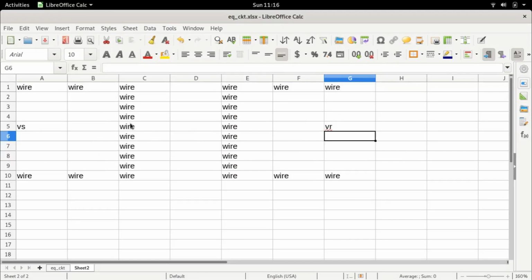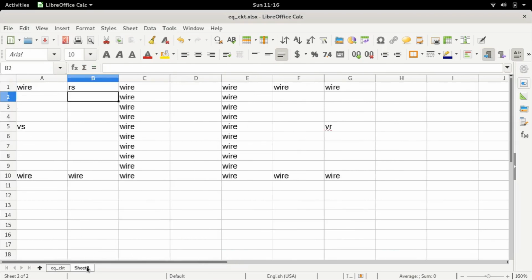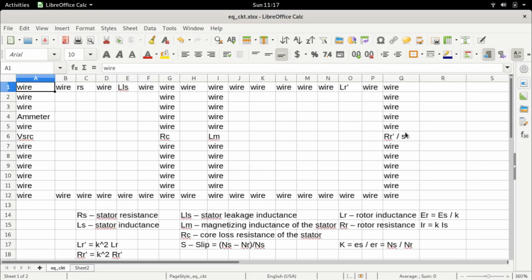So now that we have come here, of course, we know that this stator has a resistance. This is the winding resistance, and this winding resistance is exactly the same as this resistance RS here, right? Because this is merely the winding resistance of the stator. Similarly, we can say there is also winding resistance of the rotor, right? We'll call it RR. Let me write RR like this, right? And let me just write RS like this as well, right? So you can see that this RS and this RR are actually very similar, right?